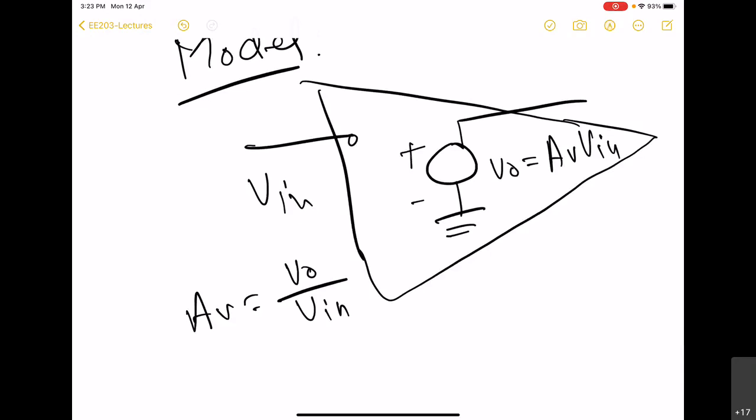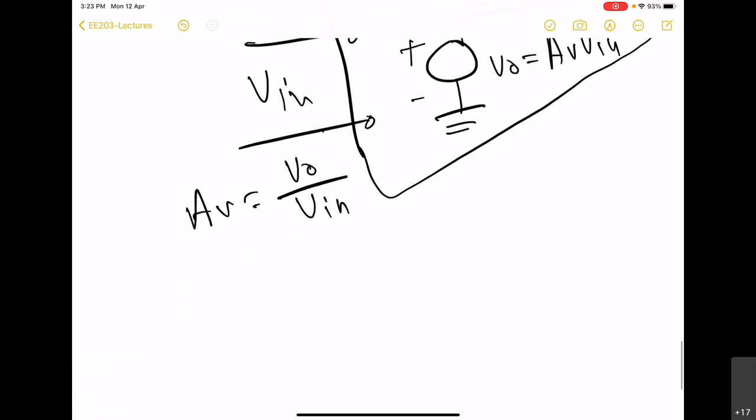So now if you recall, an op-amp has exactly this model, except that there are two nodes at the input side, but that is immaterial. It also has basically infinite input impedance and 0 output impedance, and it produces a voltage which is a very large factor multiplied with the input voltage. And we know that is called voltage gain. That is why we have used the symbol AV here.